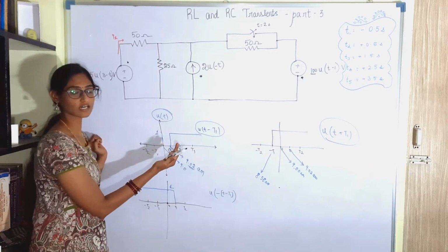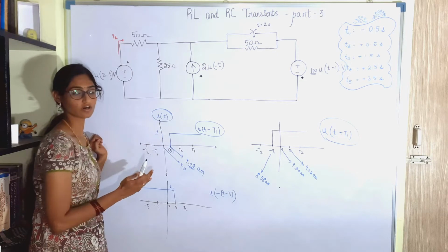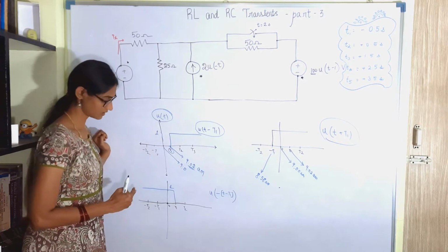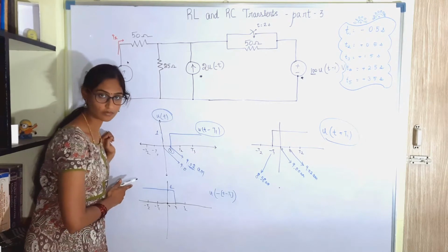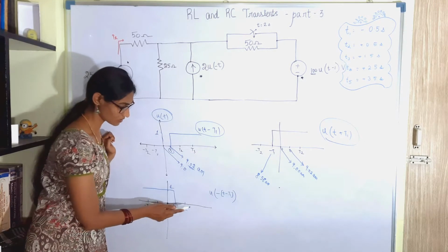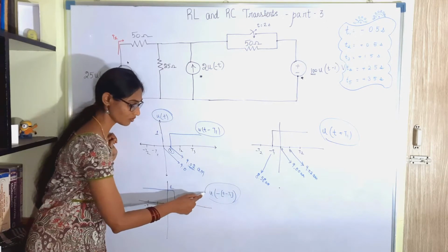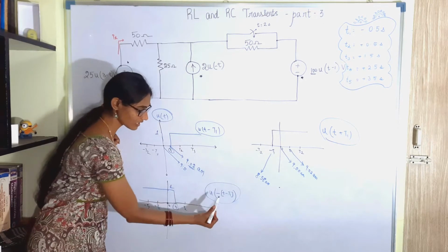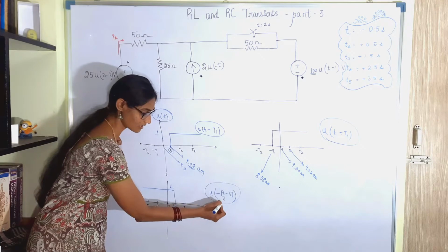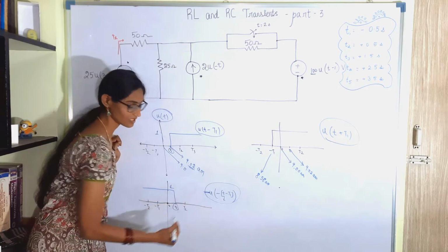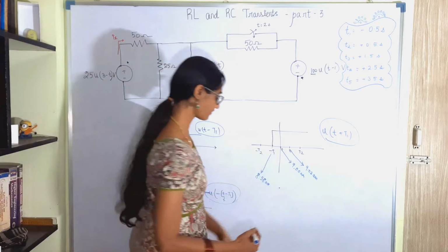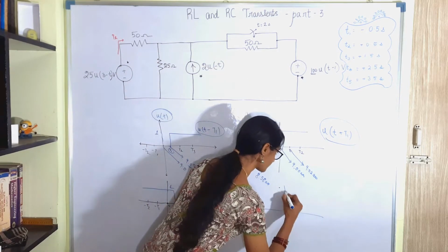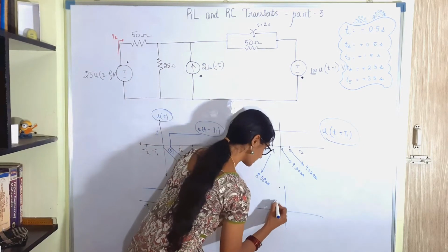So if I take a mirror image of this, or the signal that is exactly opposite to this, it should be on, or the signal should have a steady output till the time t1. So this is what this represents, u of minus, meaning that when you have a time at negative value, this unit step signal is active. That is the meaning. To a flip side of it, you can say that till minus t1, this signal will be active.